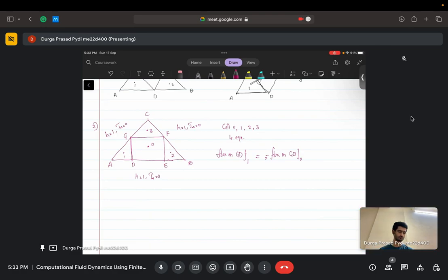I think the boundary conditions for cell 1 and 2 are the same. So cell 1 and 2 are the same. So essentially you are saying T1 equals T2. So we write equations for T1 and T0. Out of these 4 equations, T1 is essentially equal to T2, so you are left with only 3 equations. Now we have 3 equations and 3 unknowns. When we considered an orthogonal mesh, where all are equilateral, we were just having 2 equations and 2 unknowns. Now the problem is a little bit more complicated, just in that we have one more equation.